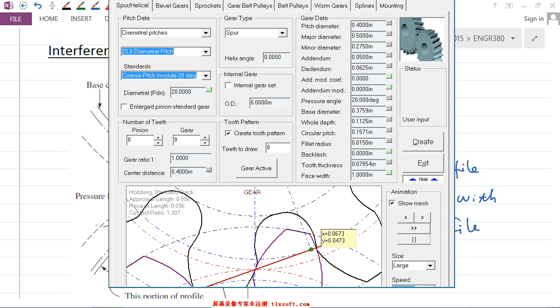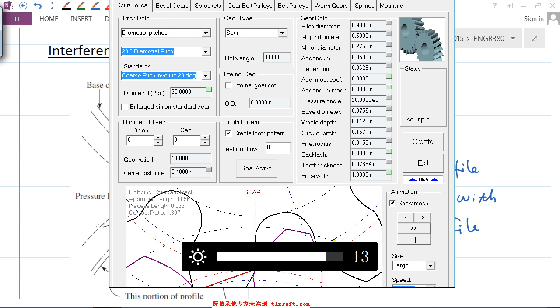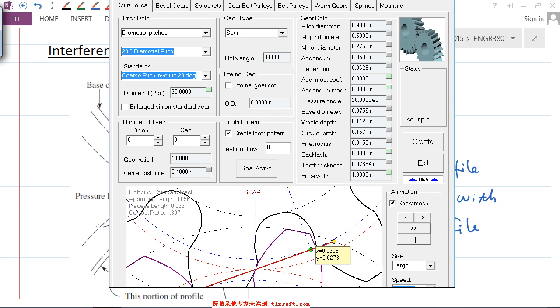Okay. So first thing is, when you want to mate the gears, the two things have to be able to mate. Mating basically means the diametrical pitch of the gear and the pinion has to be the same. Right? And then the next question is, you want to avoid interference. And avoiding interference has a lot to do with the number of teeth. When you have a smaller number of teeth, chances are you will have interference. But you can always avoid interference by having this undercut at the root location. But that's basically what I just said: you're weakening the teeth. If it's not avoidable and you have to do that, then you have to have this undercut, right?